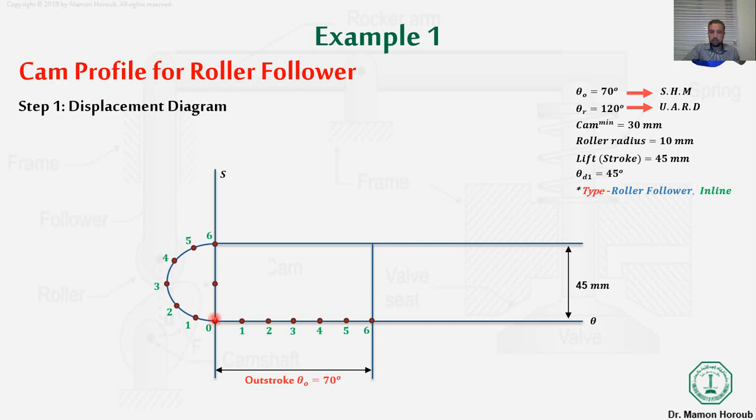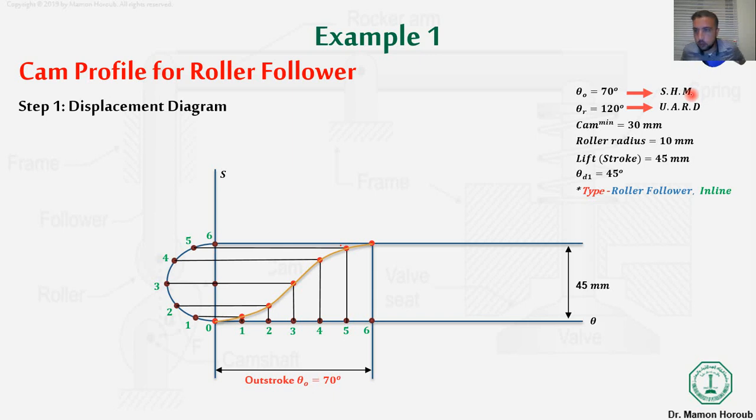Here in the first one, I will raise perpendicular lines with 90 degrees, and in the circle I will draw straight lines with 0 degrees, as we see here. The intersection between every two corresponding numbers, here 1 with 1, 2 with 2, and so on, I will mark with a red dot. I will connect those 6 red dots, and it will give me what we call simple harmonic motion. So you need to follow this procedure to draw this simple harmonic motion.